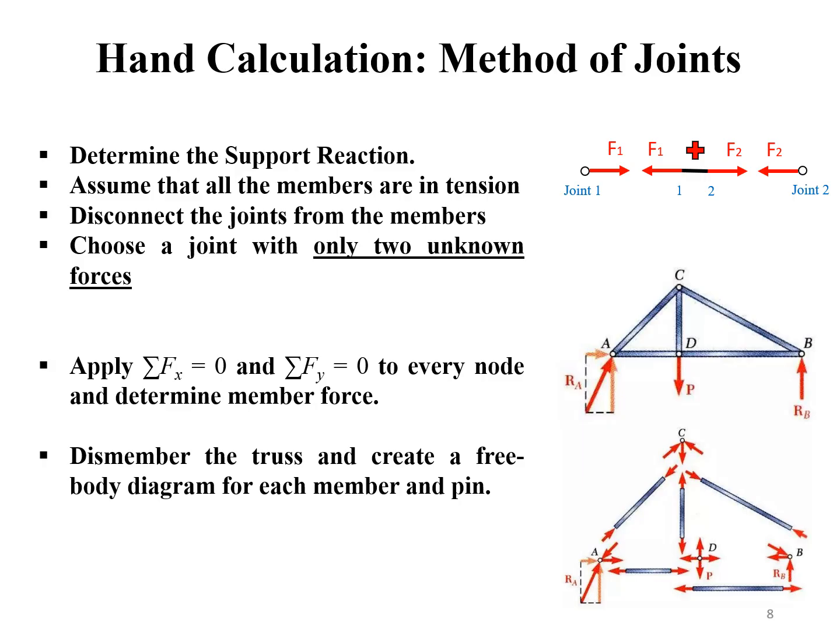For the method of joints, firstly we draw a free body diagram showing all of the external loads acting on the truss. And then we use three equilibrium equations to calculate the reaction forces. Remember that we are calculating the forces acting at each joint, not the forces in the member.